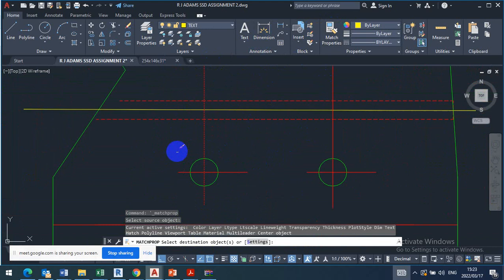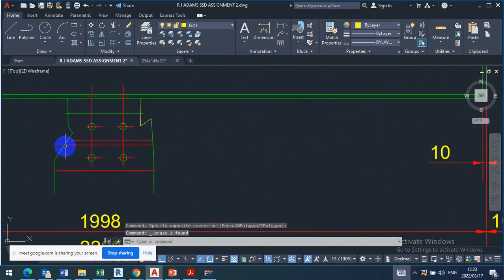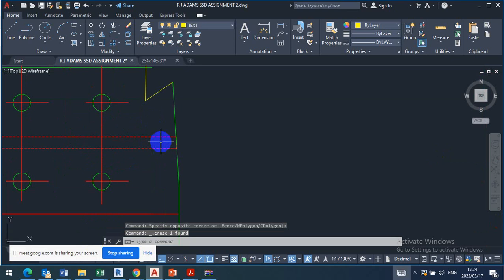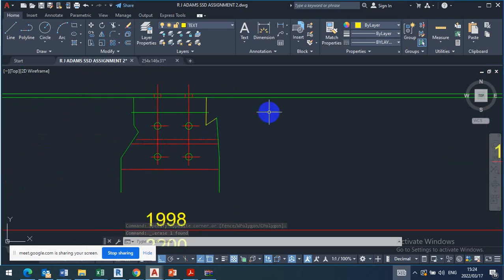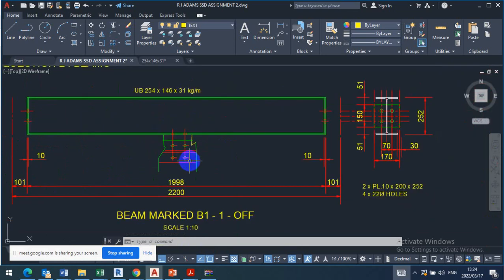So I want this one to be a center line, but this we don't need. You can just delete. This is the hidden detail for the flange, because we're looking from underneath. This is a flange, this is a web. So the hidden detail for the web is underneath. And that is where we measured from to get our G. This from center to center is the G1.